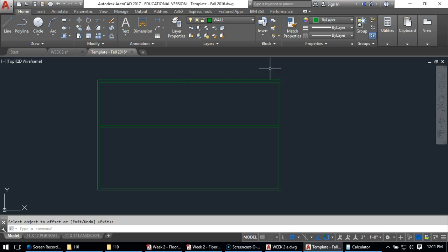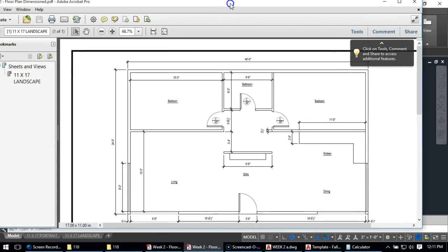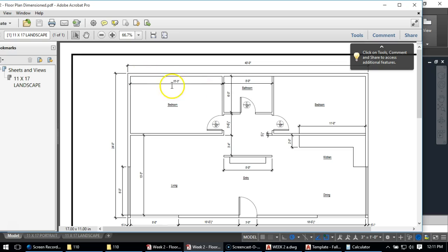And you'll notice when I look at my sheet, and this is common, so I'll mention it now, that I have this dimension here, 15.3, and I have the next room, which is 8.0, but I don't have this one. Since we know the whole building's 40 feet, it gives the contractor some leeway when they're building, so you only give the most important ones. Quite honestly, this bathroom probably should be 8 feet. That's why it's dimensioned there.